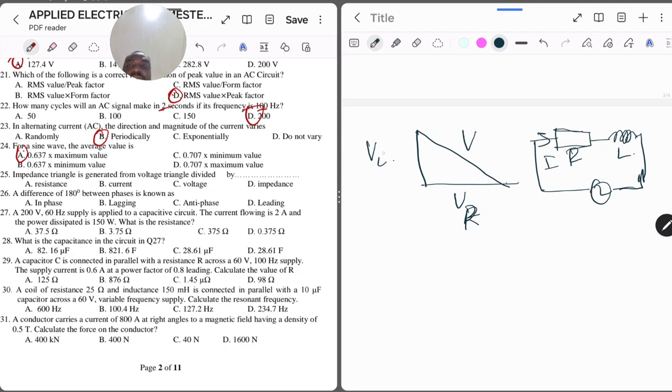So when you come to the voltage here, VL is going to be the current times the inductive reactance, right? VR will be the current, which is the same, times the resistance. And then the voltage supply here is the current times the impedance. So you can see that if you divide each of these sides by current, you end up getting only resistances, right?